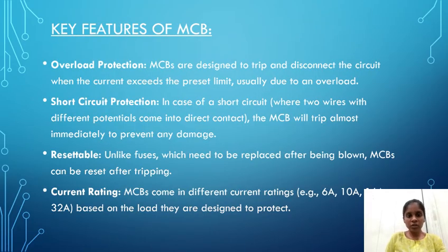Next, the features of MCB. It provides overload protection and short circuit protection. We have already discussed it. And it is resettable. I said with the example, right? Like a fuse, which we need to replace with a new one all the time, whereas with an MCB there is no need for that.